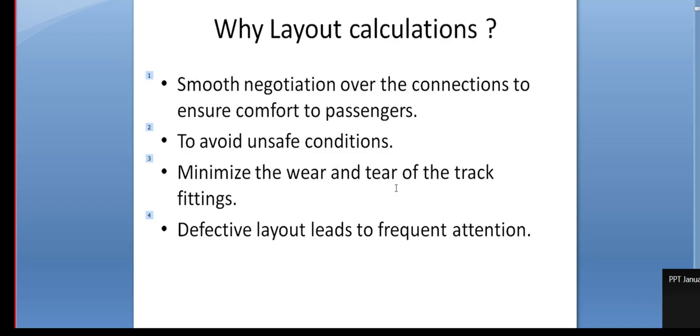So ultimately there will be setting up of vibrations. Once the vibrations set in, what will happen? The packing will get loose, the fittings will have more wear and tear and become loose, and often our keyman has to refix and we have to replace the fittings again. Formation of grooves in the sleepers, crushing of rubber pads, crushing of liners, all will take place.